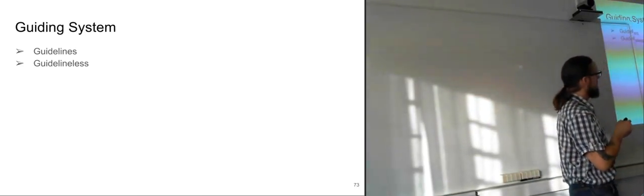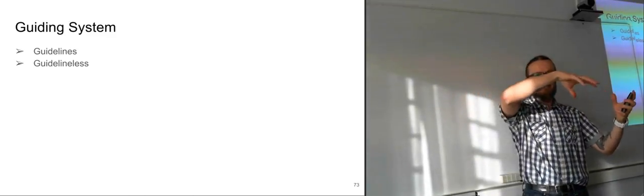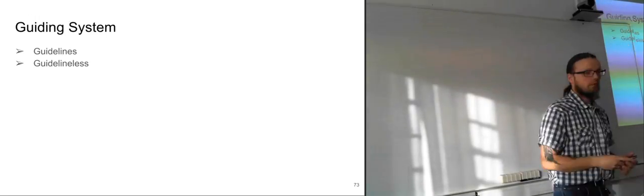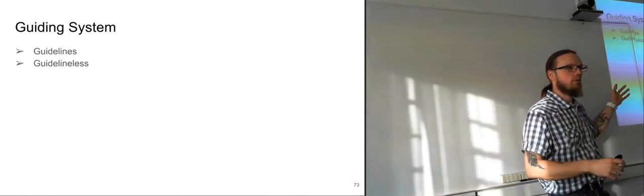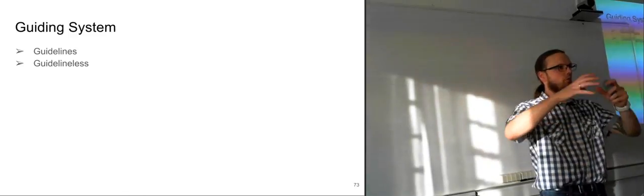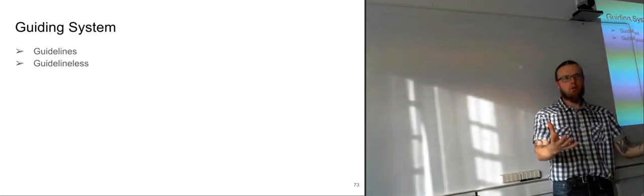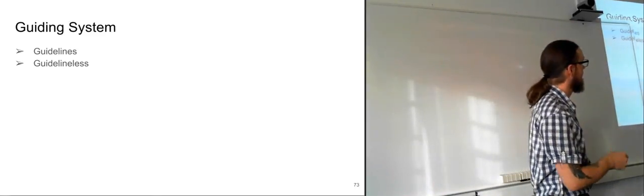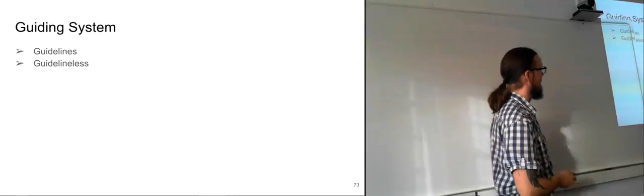So what they usually do with the guidelineless ones is that they have some sort of funnel which can catch guiding tips or guideposts. The guideposts are mounted on the base on the subsea floor, just like in the guide wire system when you have guidelines. Then the funnel will be on the module coming down. But you can also have the funnel on the base and a guidepost on the module coming down. It's just a matter of design, really, how you do it.